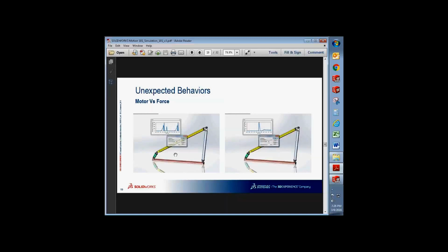So you have to decide what you want to do, because it's harder when you're using forces. Why would we not always use force or torque and skip motors? Now you have to create a special function if you want the motor to go at 10 millimeters per second, but still give enough torque. It has to be a variable torque to keep that 10 millimeters per second. It's harder. So we already have these.